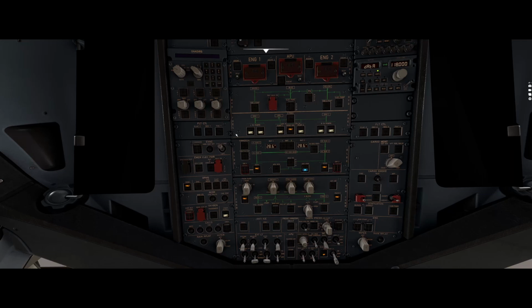Cool, once we've aligned that, we can go through our flow. So we generally start on the left hand side here. The first thing we'll do is turn our evac from capped and burst to capped. Our flight recorder, we'll turn the ground control recording system on, and we'll give that a quick test to make sure it beeps.